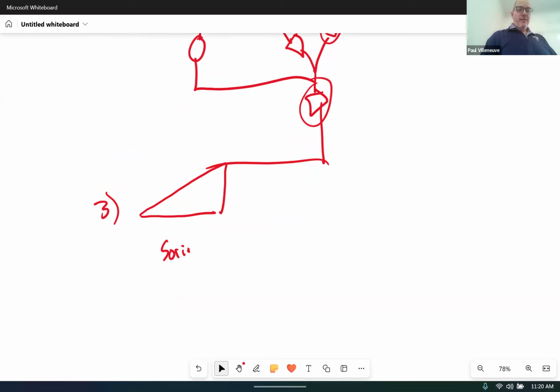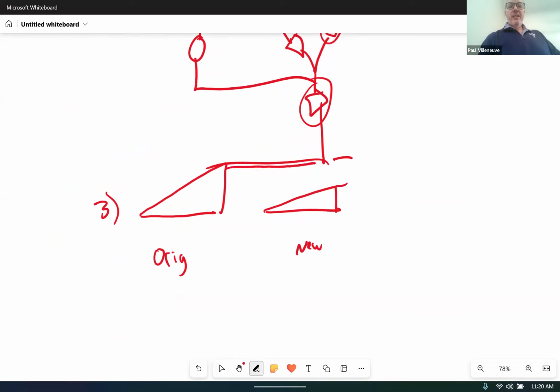We'll call it S original. You have to do 2 power triangles. And the difference between this value here and here was Q cap. So all you needed to do was build your power triangle. We had 15 megawatts. This is the inverse cosine of 0.85.